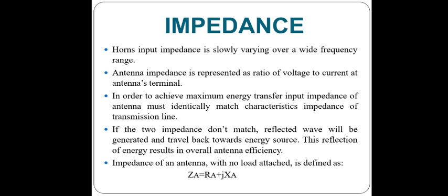There is a mismatch between the impedances. Therefore incident and reflected waves are both formed, and standing waves occur. So energy is lost, and ultimately the efficiency of the antenna is reduced. That is the main point, so impedance matching is very important.